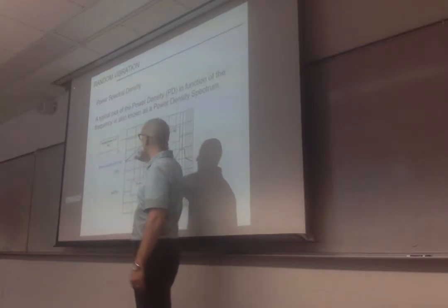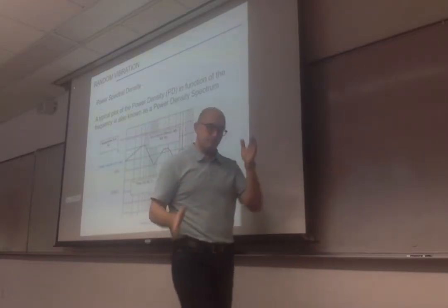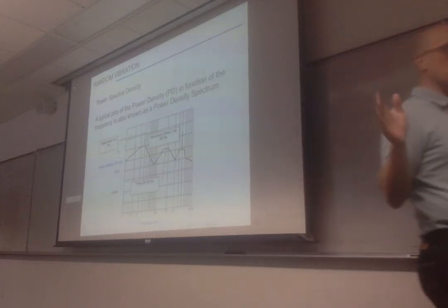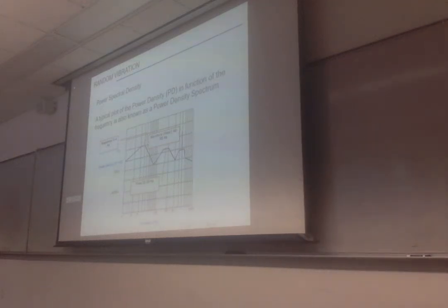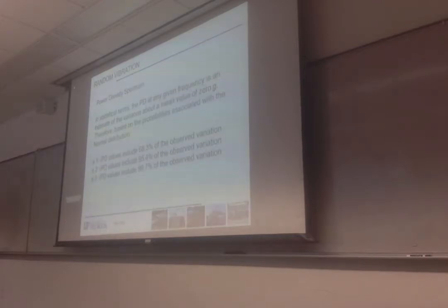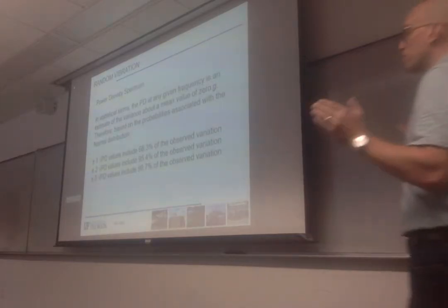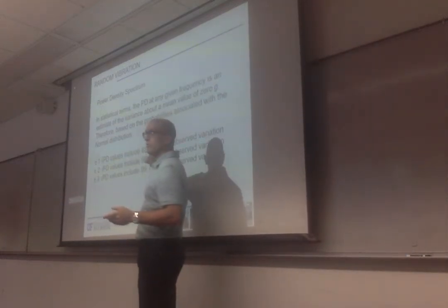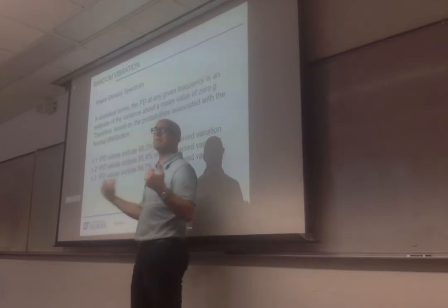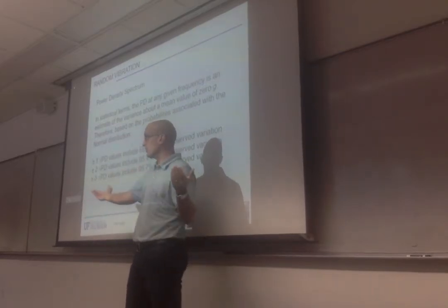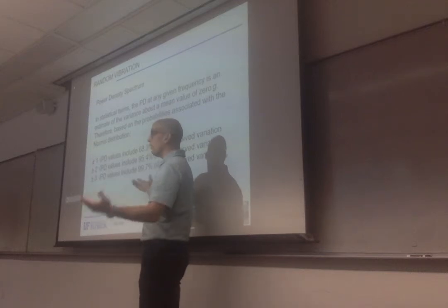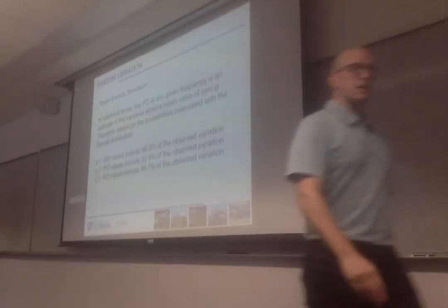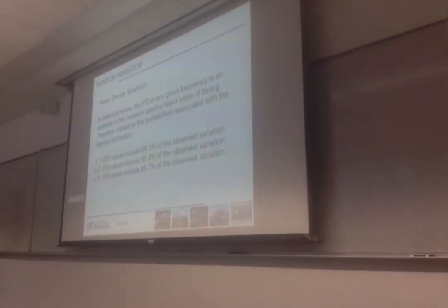So I know then, if I take that value and I create a range of plus or minus 1 time that value, so that means that all the observed acceleration I'm going to see, okay, between plus and minus 0.1 g, okay, it's going to take into account 68.3% of all the acceleration I've expected to see in those conditions. Does it make sense? Okay, and so on. So that's the idea. So I'm just going to write a few things just so it makes a little bit more sense, and we're going to stop.